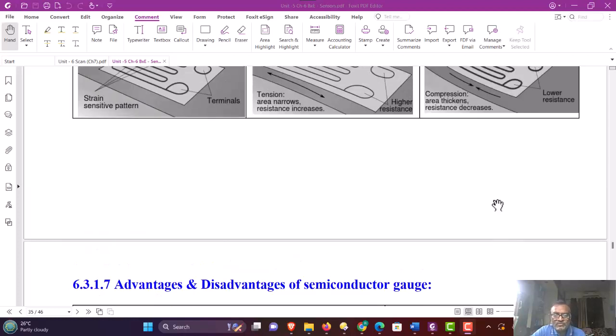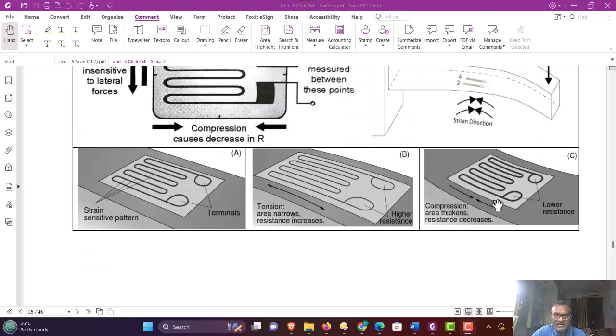So now we get from the strain gauge the pressure converted to a proportional change in resistance. If these strain gauges are connected in bridge form in the appropriate branches, then the bridge output is proportional to the change in resistance.